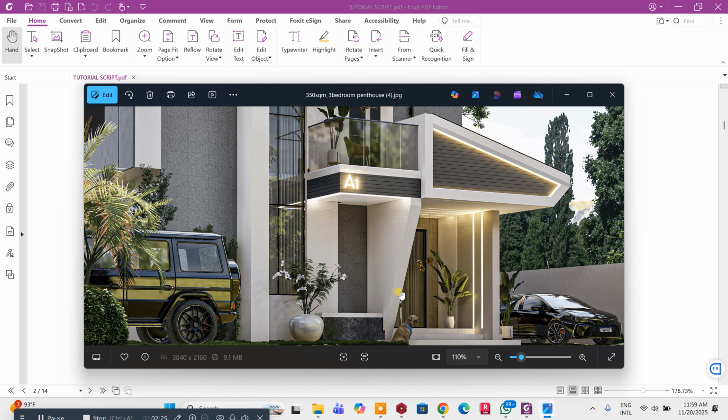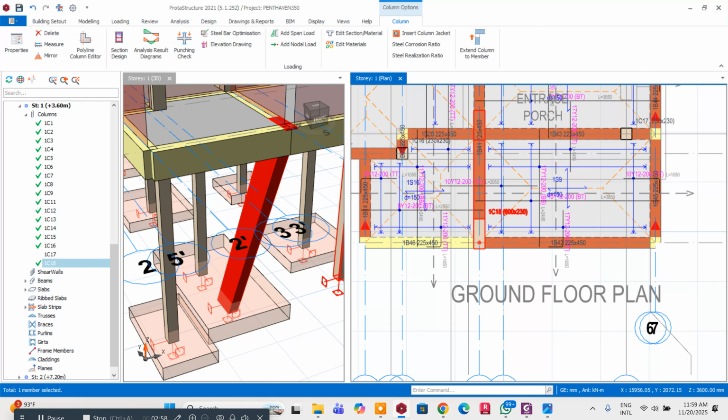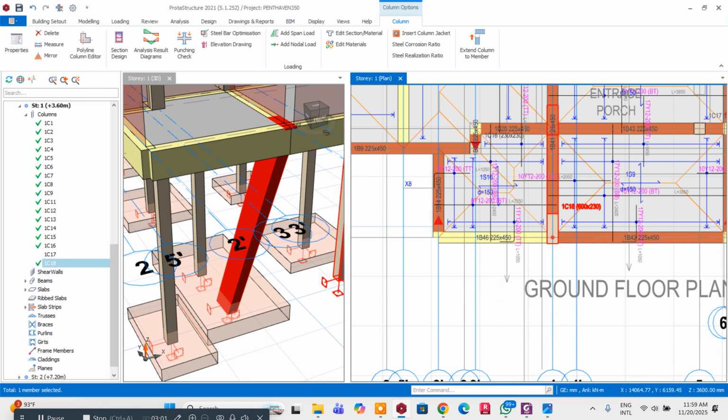So for a vertical component, if you want to design for it, you can say V, which is the vertical component, equals P multiplied by cos theta. P there is your load or force that is going to be applied by the beam on the angle formed. And the horizontal component is P multiplied by sin theta, where P is the force or the load. So I don't want us to do much about this. The next thing we do is to go to the practical aspects.